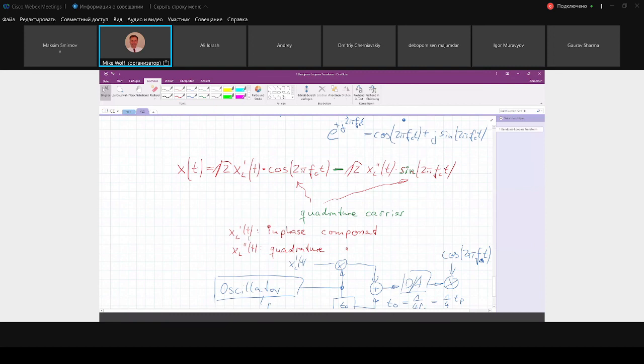And then usually today, if you build such a homodyne receiver, you sample the signal which is down converted with a cosine and put this on an analog to digital converter. Then the signal which is down converted with the minus sine wave, so with the 90-degree phase shift, goes again to an analog to digital converter. Then the whole processing after these two analog to digital converters says I take the one signal, digital numbers 1, 2, 3, and add plus j times the other, and then you have the complex signal.